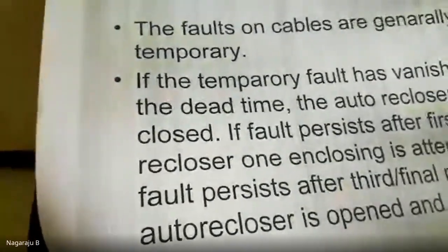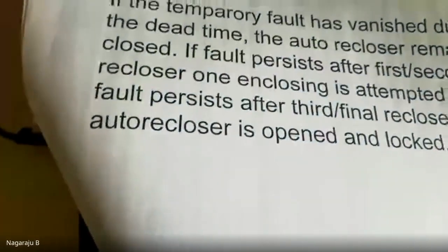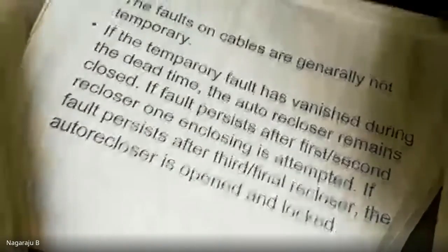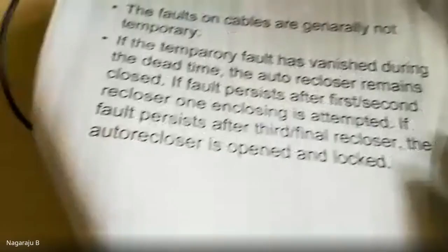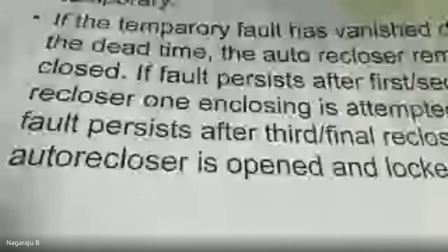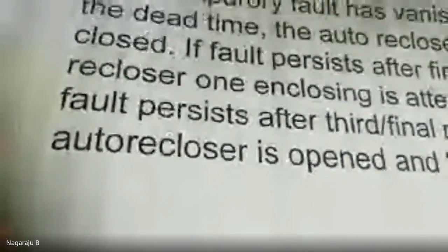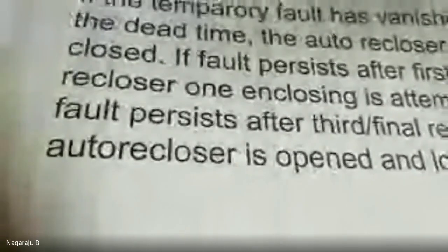After the third and fourth iteration also, if you again have a fault, then automatically this auto recloser is going to open and lock out. Okay, this is about the auto recloser.